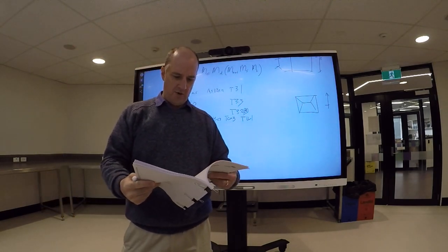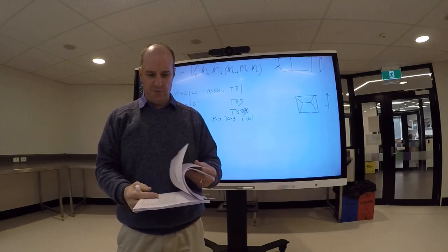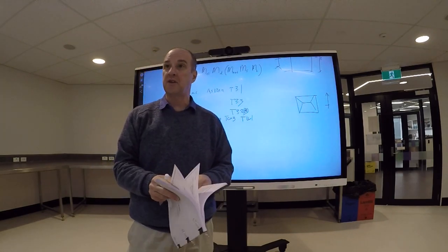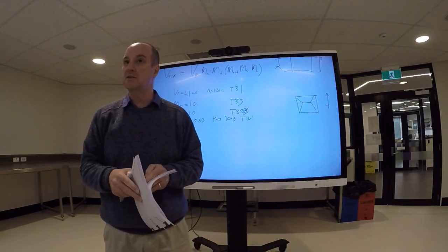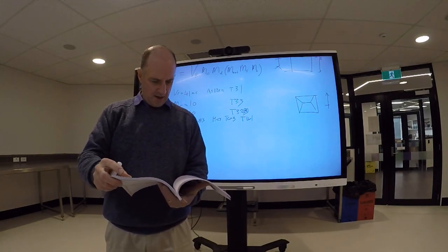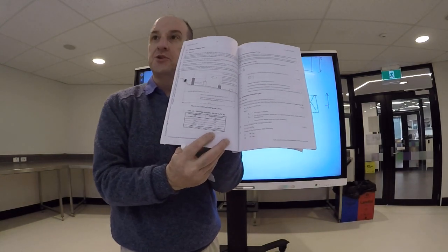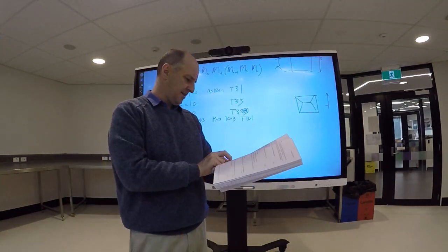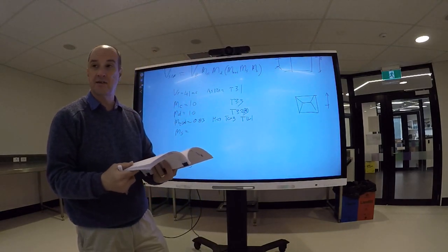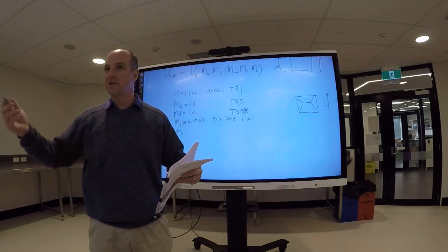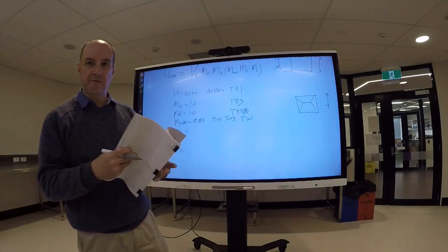MS is a shielding multiplier. If you build a house and it is surrounded pretty well by lots of other houses, then you get to downgrade the wind speed. The shielding multiplier is over here in table 4.2. If you want to consider shielding, you've got to consider how big is that building beside yours, where is it in relation to it, how far away is it. And there's a bit of formula there.